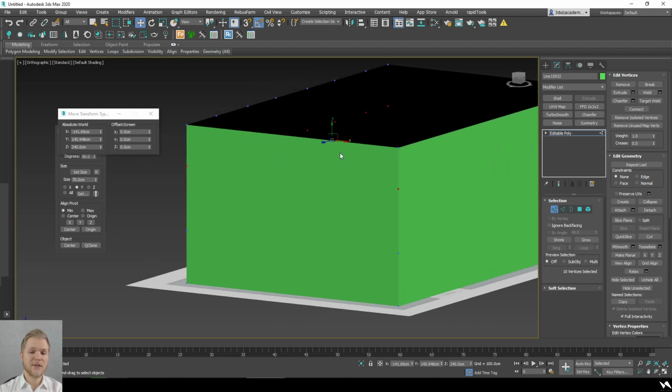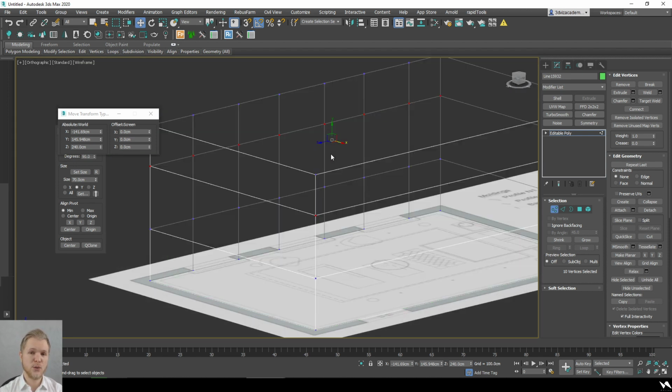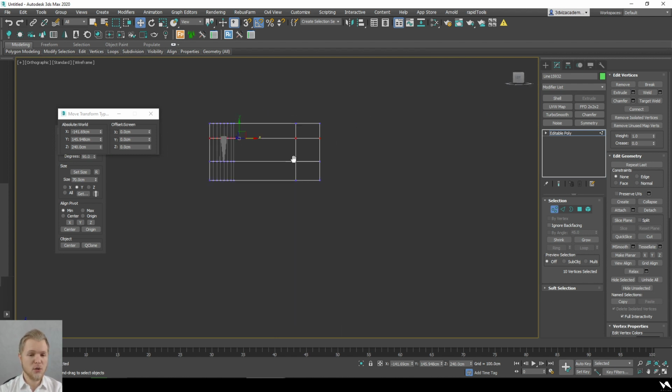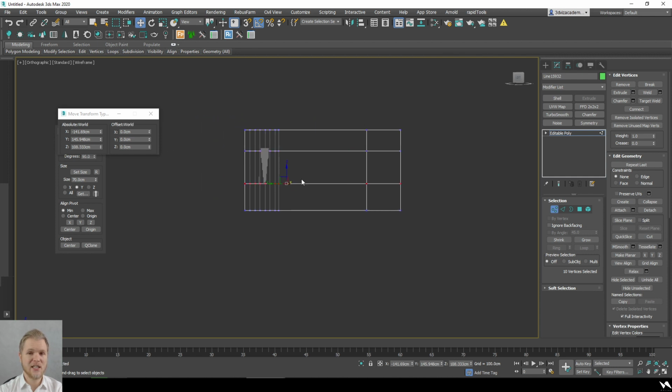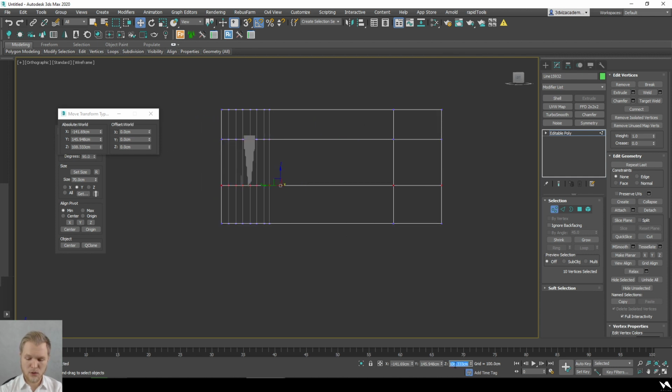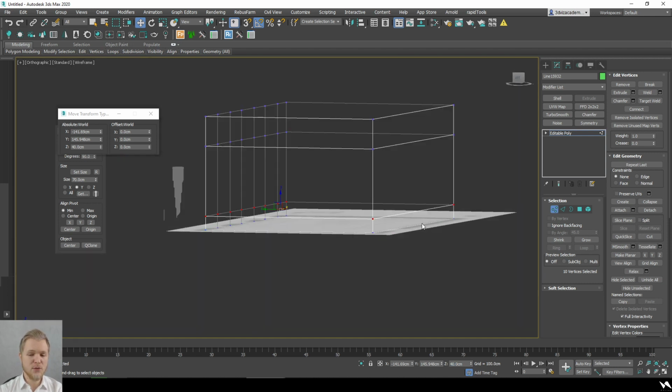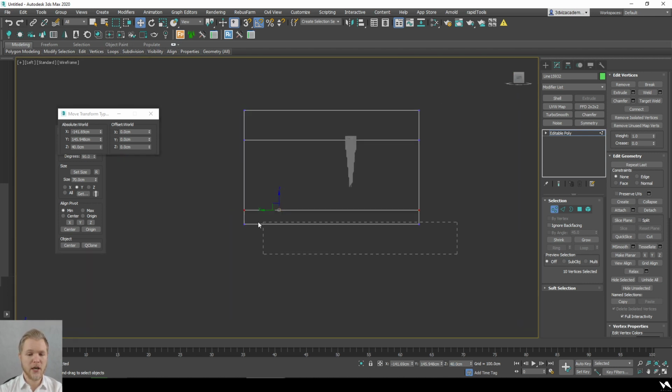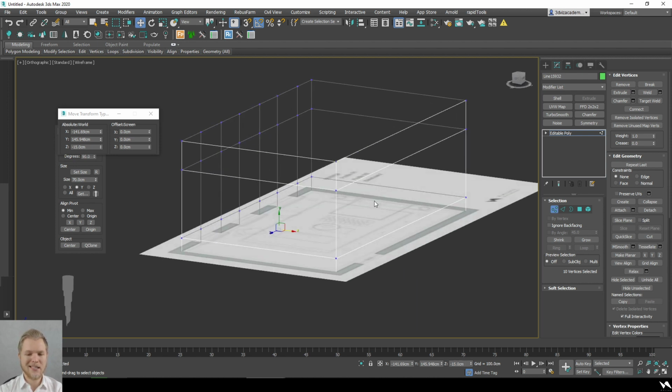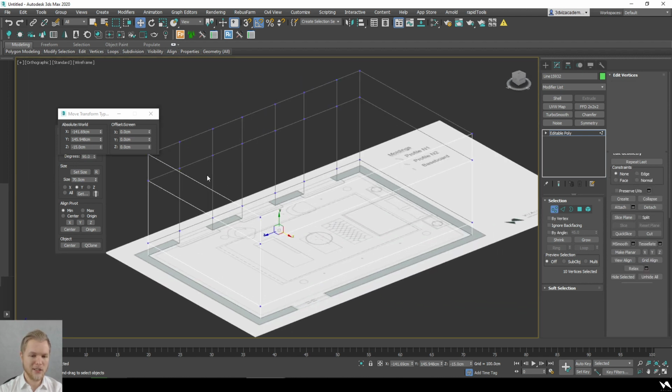I'm going to set up my windows height to 240 centimeters, and I want them to be 200 centimeters tall. That's why I'm going to put the bottom of it at 40. So just to avoid any problems with light intersection, I'm going to make sure that my ground level is actually going to be lower than 0. So in this case, I'm going to type in -15, but it's not going to play a big role in my scene.